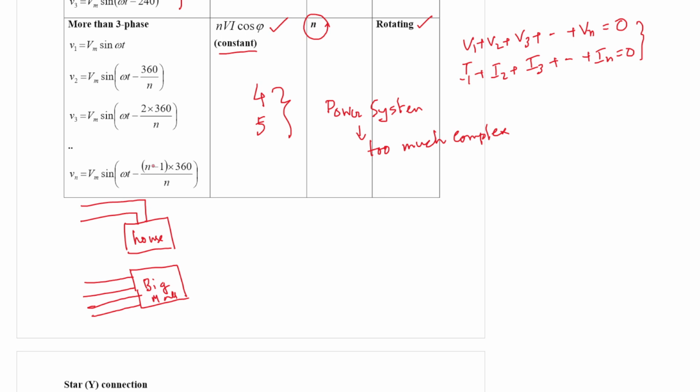So this is of course R, Y, B and N. This 3-phase supply must be given to that mall in order to cater to all the loads. However, for your house you need not any separate supply. You can just tap one phase and neutral to take supply from that source.